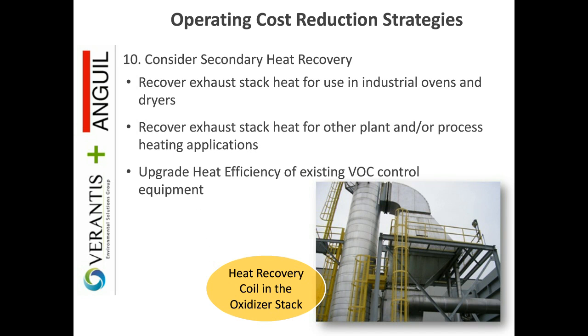Secondary heat recovery. One thing to keep in mind is this always seems like a pretty good idea, and for some technologies it does really work well. For example, like the direct fired system, you have going out the exhaust stack, it can be 1,500 degree air going out the exhaust stack, so you can have a lot of energy there. Now on the RTO side, the RTO is designed to be internally energy efficient. So the majority of the heat is kept internal, so it's more applicable to the less efficient technologies.